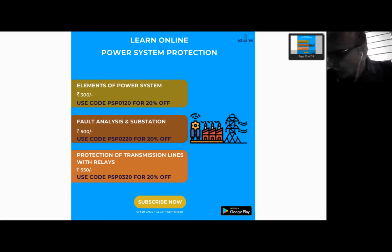This is for which application we can use distance protection. There is a case study in our plant. We are using distance protection for bus bar plus cable for just 1 kilometer length. What will be the effectiveness of distance protection? I would like to mention that we are using differential protection plus OC protection also.